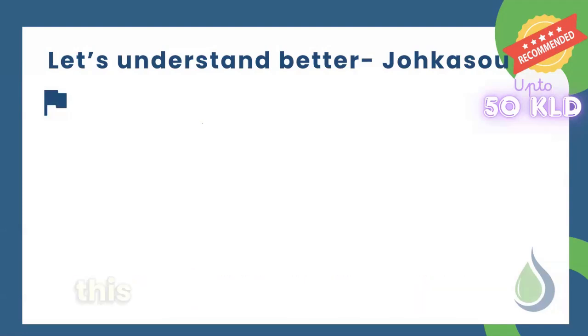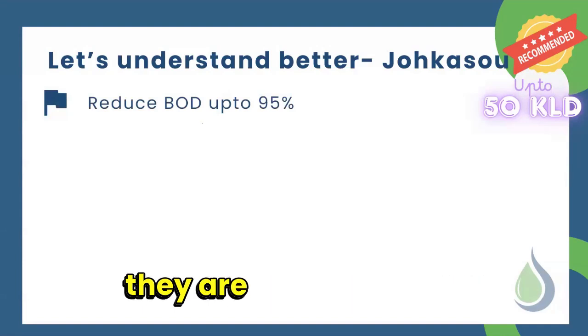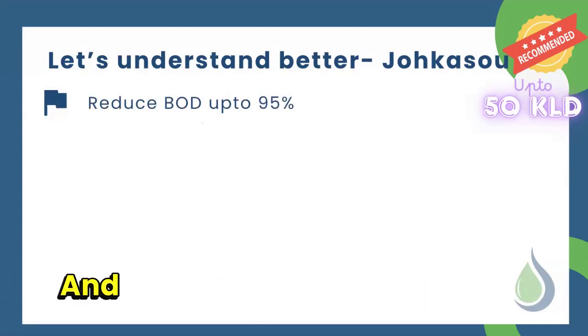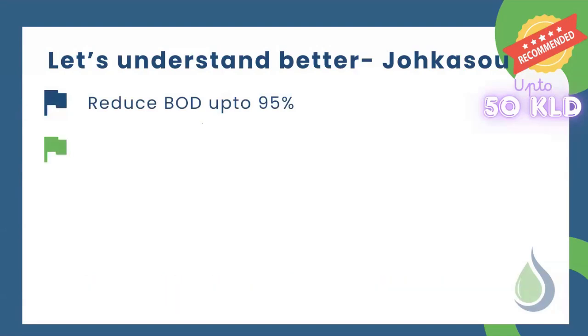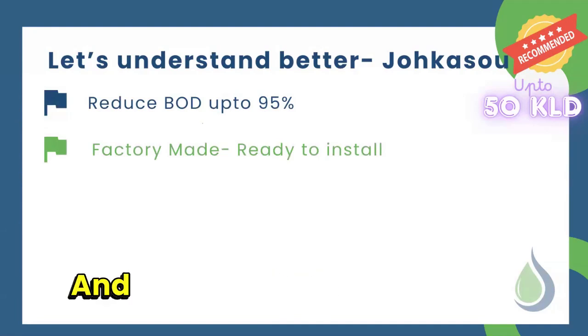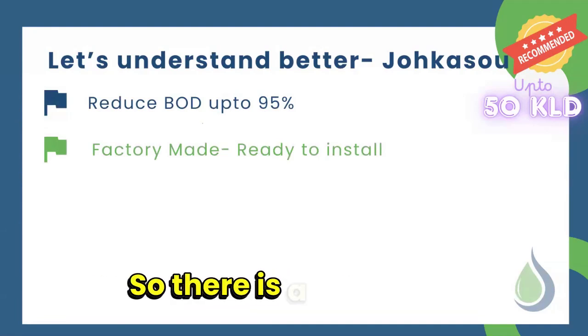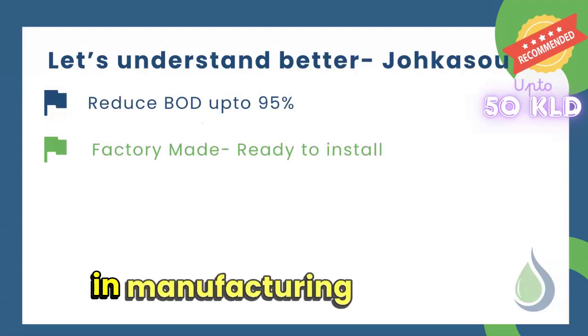And the biggest advantage of this is they are very compact, they are factory made, right? And they reduce BOD up to 95%, right? And they are all factory made. So there is a standard in manufacturing.